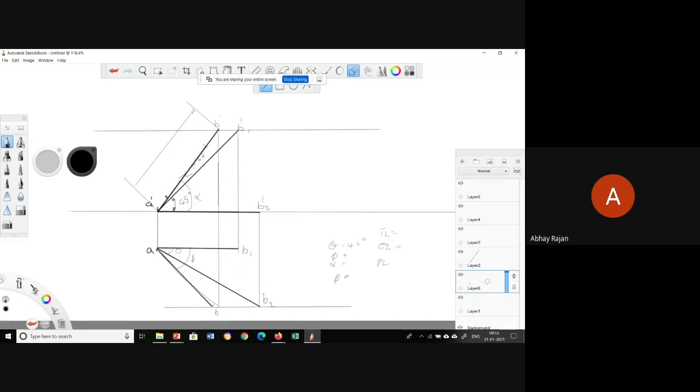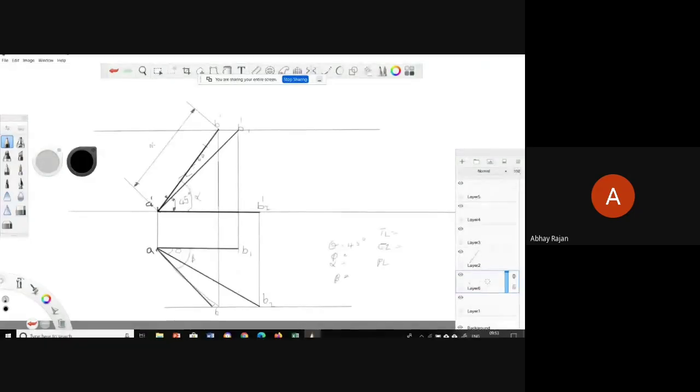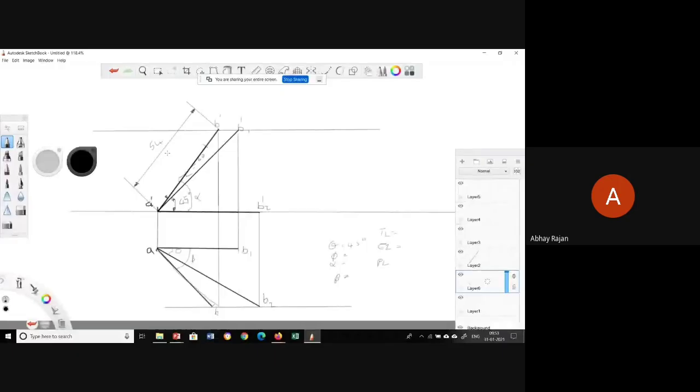That is how we talked about dimensioning. Similarly, do the dimensions properly so that it will be easy for people to understand your drawings, right? You give it like this, and you can measure this length and say this is 54 mm. You can letter 54 mm.